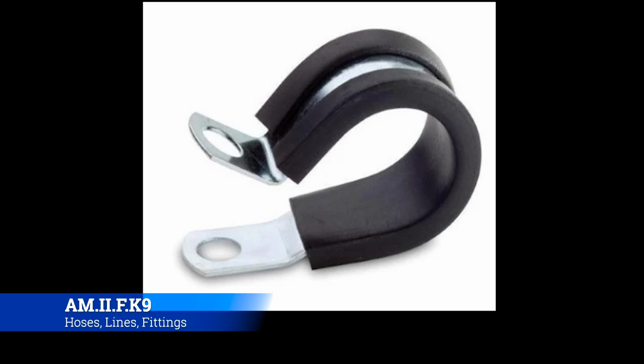Now, there are some special tools that will make your life easier. You don't have to have them. There's a lot of tricks to zip tying off the clamp. You put a screw through there and you zip tie it off so it holds itself in place, or use safety wire for it. I've done all of it at some point or another. It's whatever will hold that clamp together while you manipulate it and get it all installed. But there is a pair of vice grips that has a special nose on it that will clamp down and hold those clamps in place.